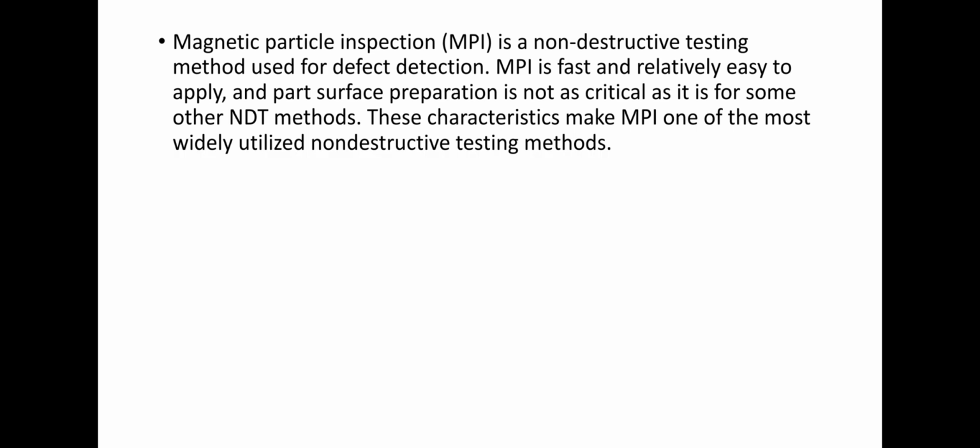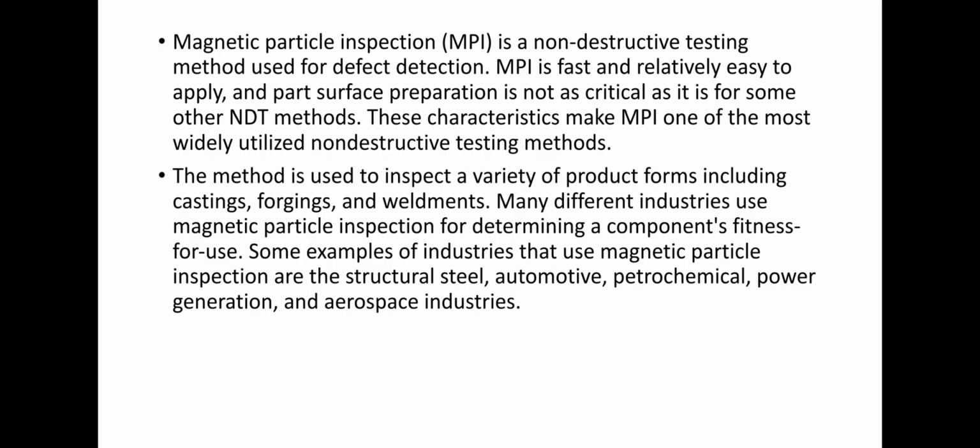Magnetic particle inspection is a non-destructive testing method used for defect detection. It is fast and relatively easy to apply, and part surface preparation is not as critical as it is for some other non-destructive testing methods. These characteristics make magnetic particle inspection one of the most widely utilized non-destructive testing methods.